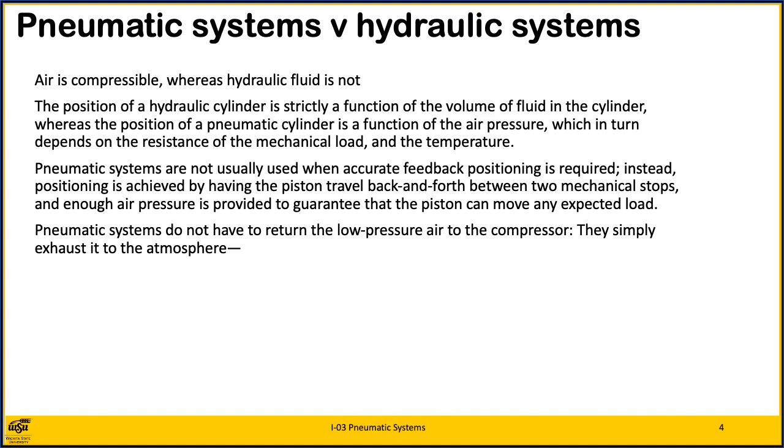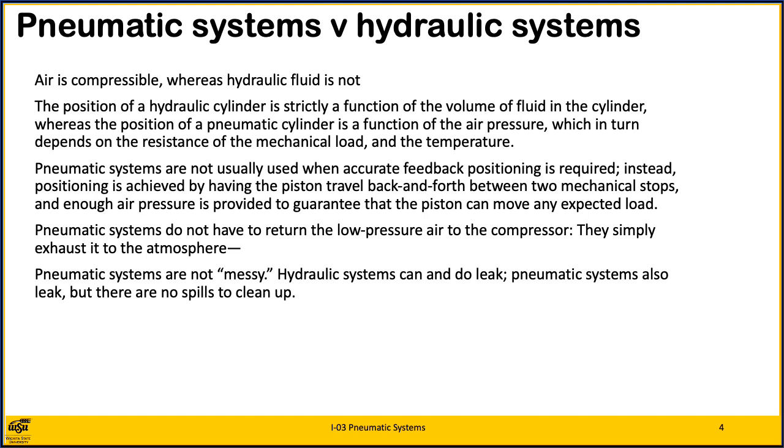Another difference between hydraulic and pneumatic systems is that pneumatic systems do not have to return the low pressure air to a compressor. They simply exhaust it to the atmosphere, clearly an advantage. Another advantage is that pneumatic systems are not messy. Hydraulic systems can and do leak. Pneumatic systems also leak, but there are no spills to clean up. Also, pneumatic systems tend to be smaller and less expensive. All these qualities make them very attractive as a source of mechanical motion in cleaner, high-tech industrial environments.